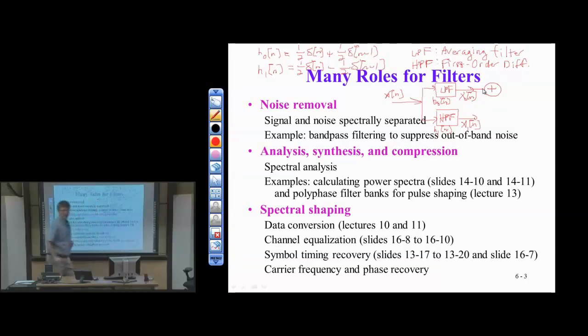And again, provided that we have a linear time invariant system here, which means that initial conditions in both the low-pass and high-pass filters are 0, which means to say that the initial value of the previous input for the low-pass filter and the previous input for the high-pass filter is set to 0. And that's what enables us to talk about impulse responses anyway. We need to have an LTI system, and initial conditions must be 0 to satisfy the property of linearity and time invariance. So for this LTI system now, we can look at the input-output relationship.